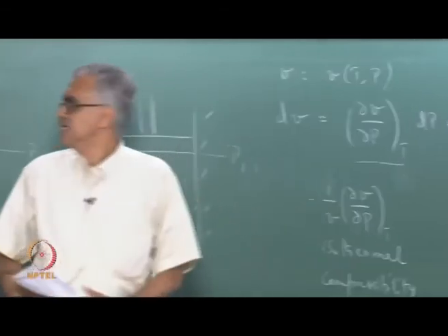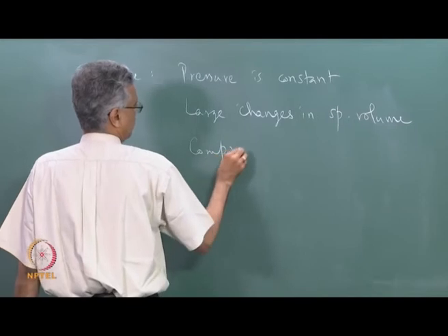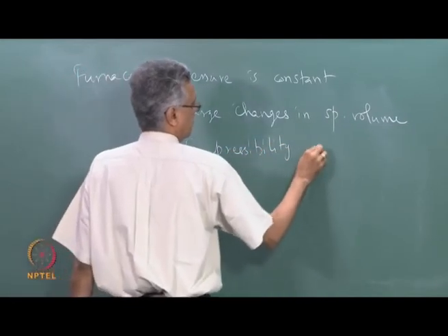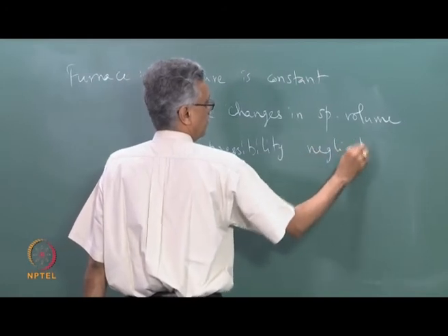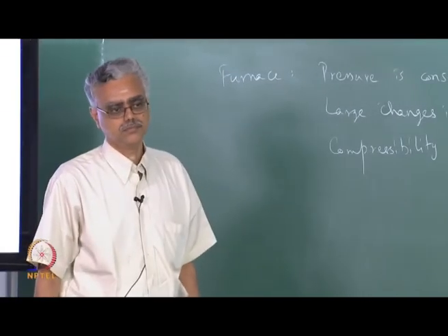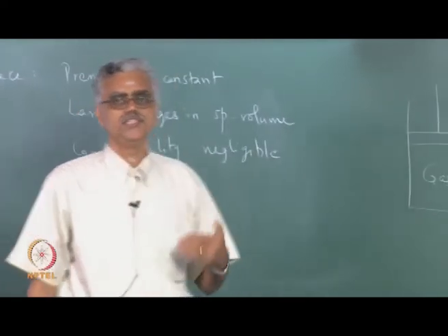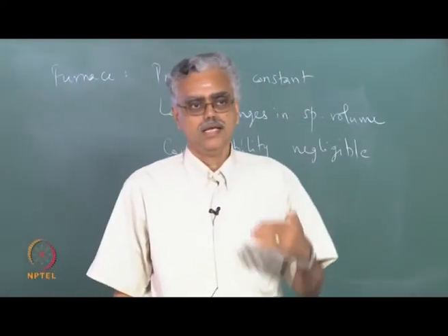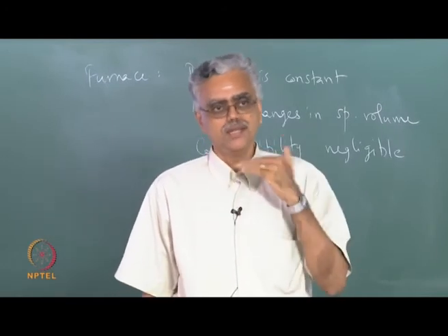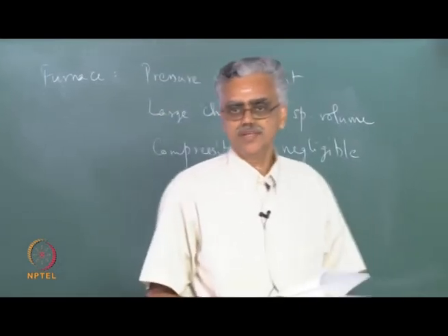So that means in this case compressibility effects are negligible. So the important point is you can have large changes in specific volume, but if the change in specific volume is largely due to a change in pressure, then we say that compressibility is important. Otherwise compressibility effect is not important.